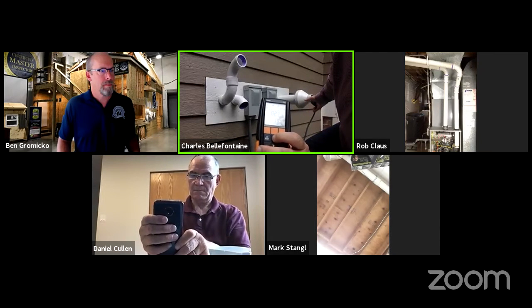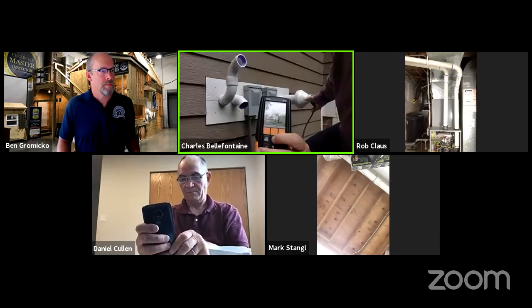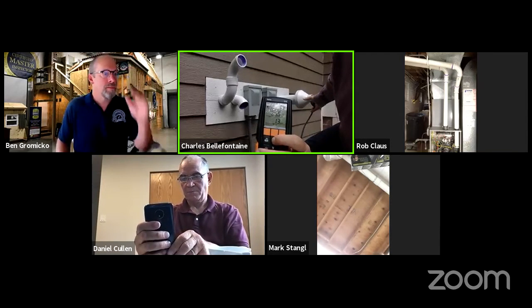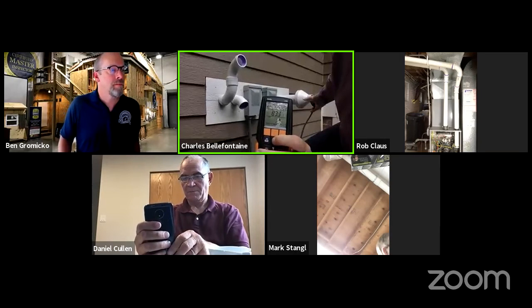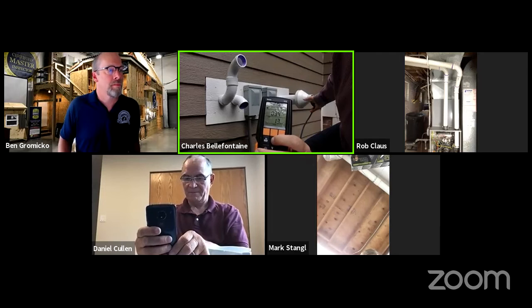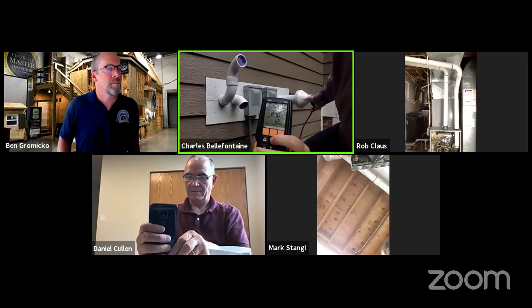So this is my temperature that's coming out. We're at 82 or 84 degrees. And like I said, we're using 95% of the heat. What's kind of hard to realize is that vent pipe that Rob mentioned that you should be touching, and that's only on high efficiencies, mind you. It is going to be really hot on the mid efficiencies, but that's going to actually be cooler than the ductwork that goes through it.